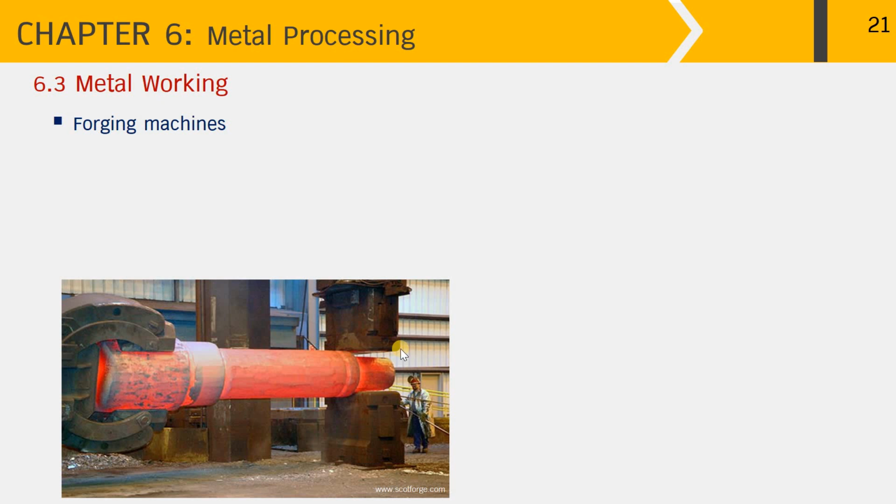And this hot forging operation has been done using open die forging, as you can see, with the upper die and the lower die. At the other end, the machine will rotate these big columns so that the reduced section towards the end can be obtained.